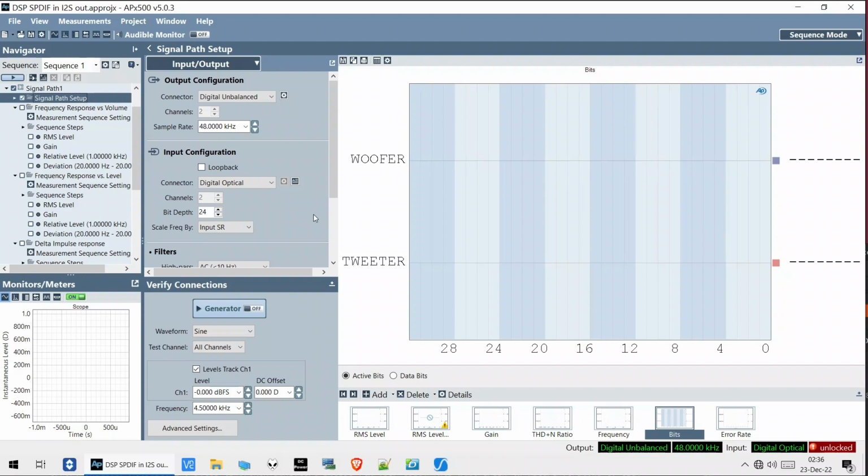As a little resume, the Philips DSS930 applies the volume partly in the digital domain and partly in the analog domain by engaging transistors that gain down the signal, I think about 8 dB, and all the intermediate steps are done in the DSP. So the DSP is aware of the system volume, and it uses this in order to change the DSP processing when the level gets louder, and I'll show you that here.